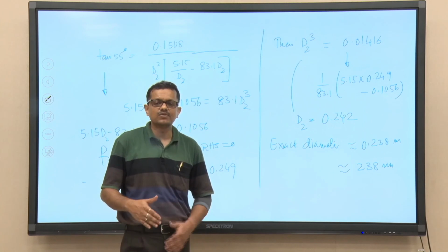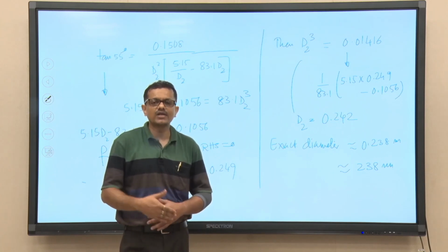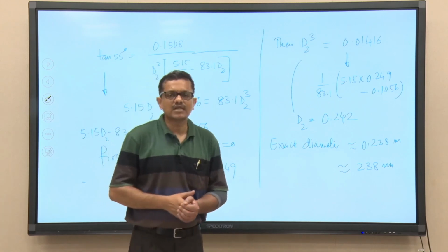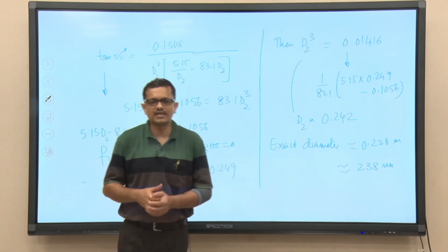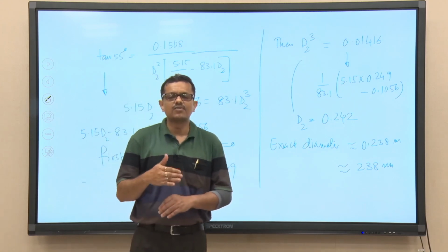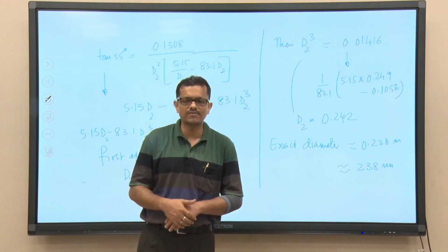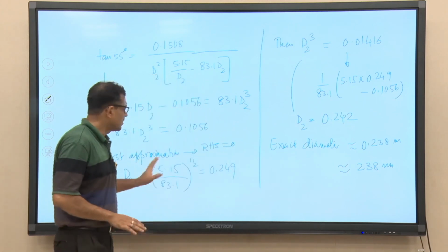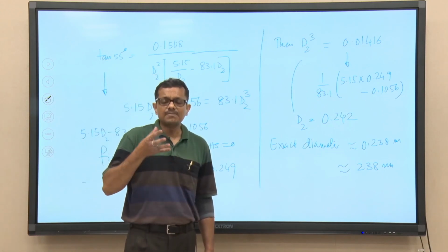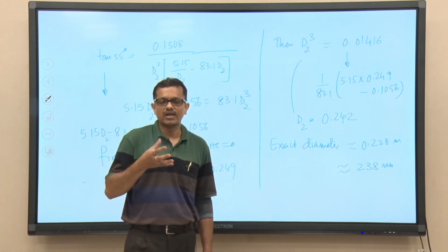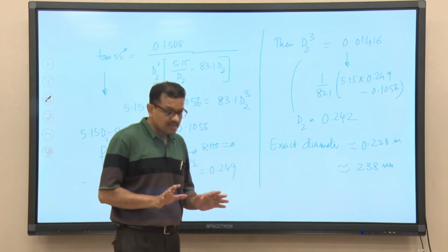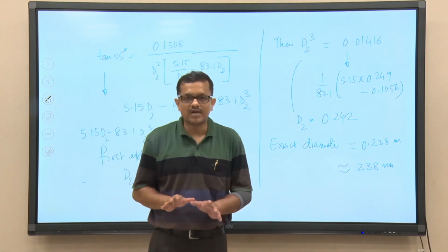So, our objective should be, while calculating total losses, to calculate the loss due to friction by taking 4 times the fanning friction coefficient. As I said, though other practical aspects remain the same, they still differ from the perspective of accuracy while calculating the frictional loss. And we have seen that knowing all those things, what helped us a lot is the velocity triangle at the outlet. It is also important that it was mentioned that there is no swirl component.